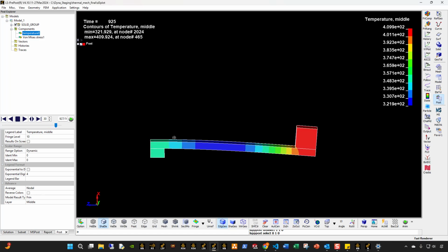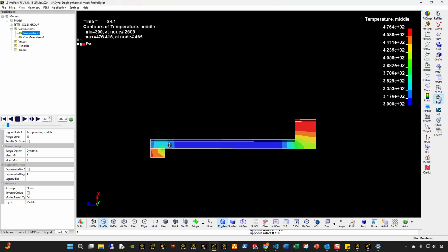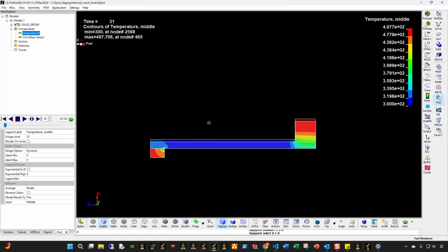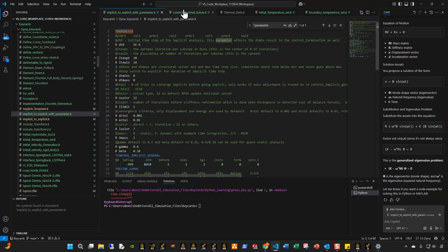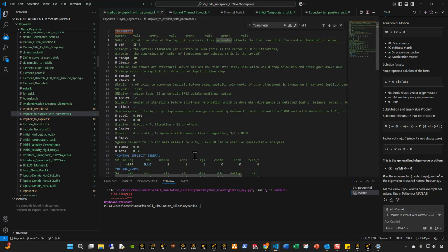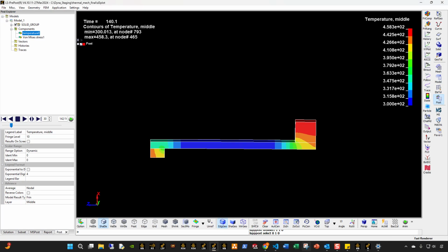So as you know, if you can change the stiffness of the material assigned to the beam based on temperature, we basically have a strongly coupled thermomechanical problem. And it is surprisingly easy to set up inside LS-DYNA, even though the GUI doesn't have the functionality yet to directly do it. What we can do, as I've always done, is to use a series of template cards, which is going to essentially create this model for us. So I'm going to do a quick demo, and I'll do a quick explanation.